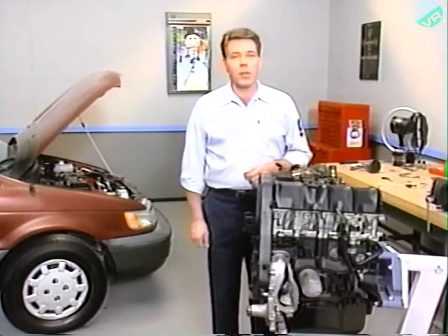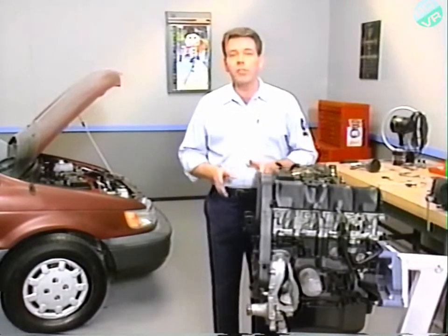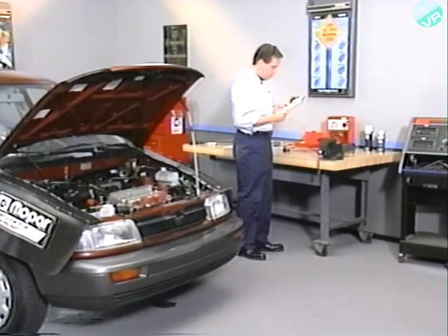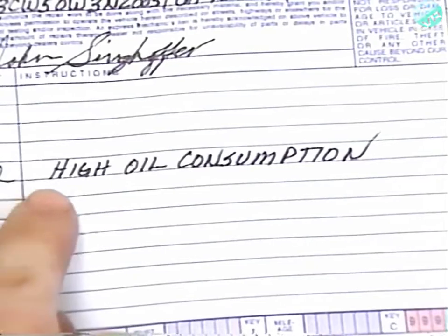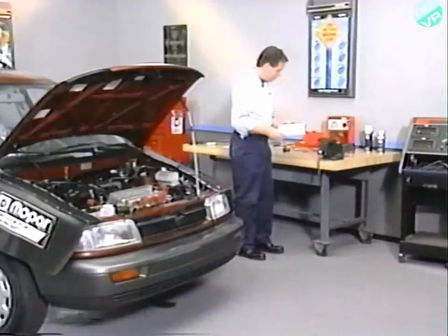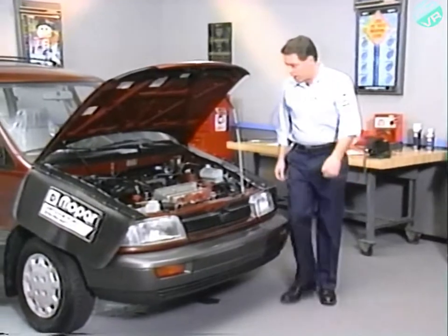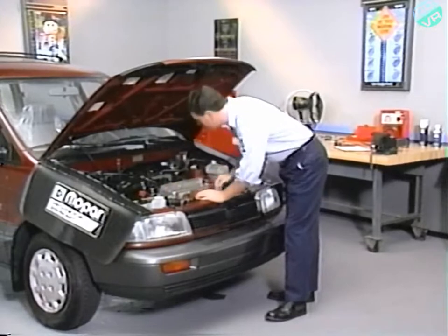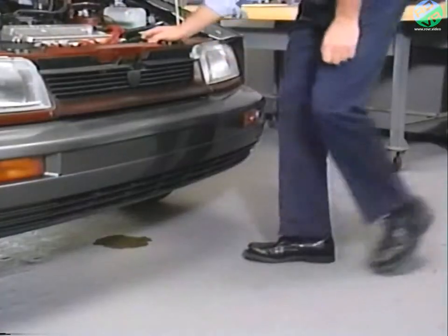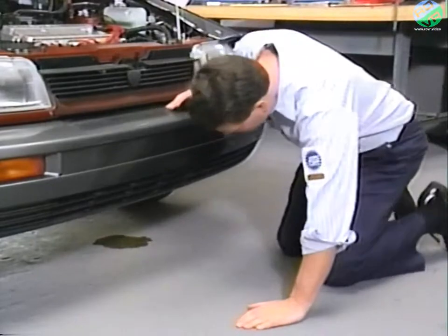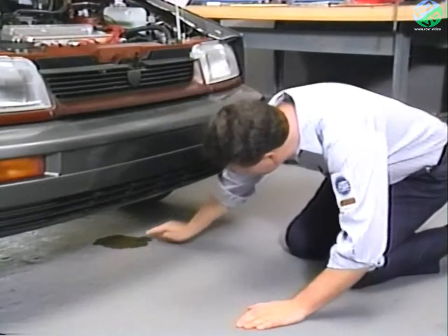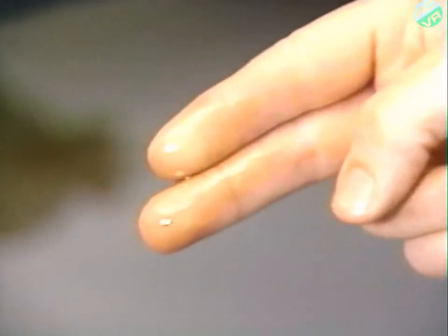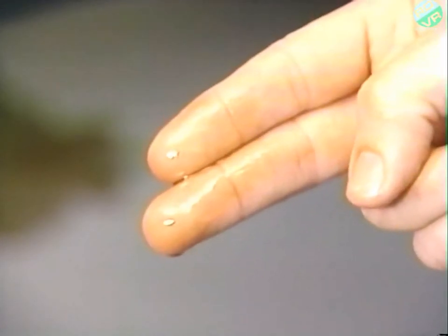When a customer's vehicle is brought in for repair, the first step in a 6-step troubleshooting sequence is to verify the customer's complaint. In this case, the customer complains of high oil consumption. Even though this particular problem can be difficult to verify, your diagnosis should always begin with a thorough visual inspection. Oil leaks are a common cause of high oil consumption, so begin by checking for oil or other fluids dripping from the vehicle. If you do find a leak, check the color of the fluid being lost.